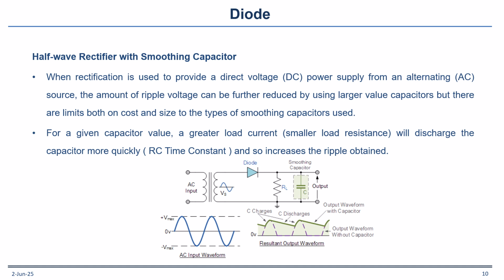Then, as you could see, we had a lot of voltage oscillation. It goes to maximum and minimum, so we should somehow solve that issue. So we have a half-wave rectifier with a smoothing capacitor. We install one capacitor here, and that capacitor has a smoothing effect. When the voltage goes up, it charges, and when going down, it discharges.